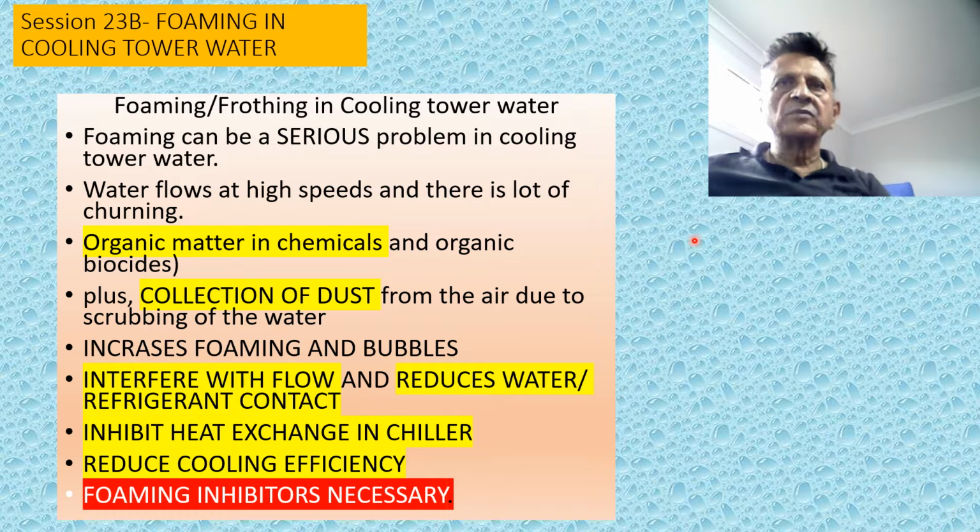What frothing and foaming does is they create very tiny bubbles which have a very high surface area, and therefore they reduce the surface area of exposure of water to the heat. In other words, the bubbles become non-conductive to heat.